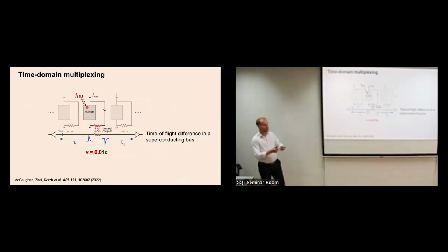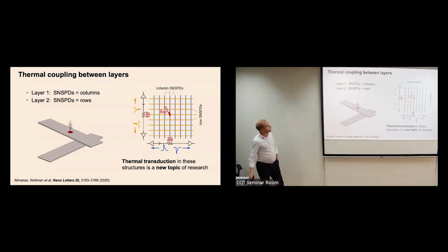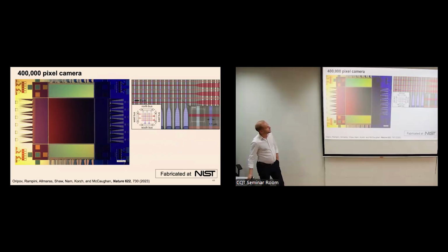So again, this is very much inspired by the differential readout of the SNSPDs. You can then resolve where along this wire the event happened, and you can tell which pixel fired from that. We call this a thermally coupled imager. I won't go into detail on this; you can pull me over later on. But the basic principle is the same: you can use this thermal coupling to couple a lot of wires against each other.